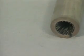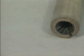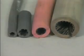In addition to affecting the allowable ampacity of a conductor, insulation also affects a conductor's voltage rating. A conductor's voltage rating is the amount of voltage that the conductor can handle without its insulation breaking down. In general, the thicker a conductor's insulation, the higher its voltage rating. But insulation materials vary in their ability to insulate. So both the thickness and the composition of a conductor's insulation affect the conductor's voltage rating.